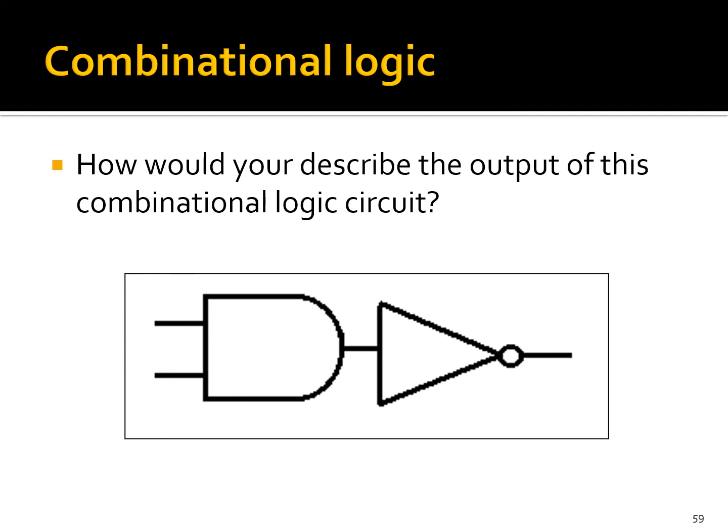So in my AND gate, if any of my inputs is 0, my output is 0. Once the output from the AND gate is 0 and it goes through the NOT gate, the output becomes 1. But if both of them are 1, then the output from the AND gate is a 1, and that goes into the NOT gate and becomes a 0.